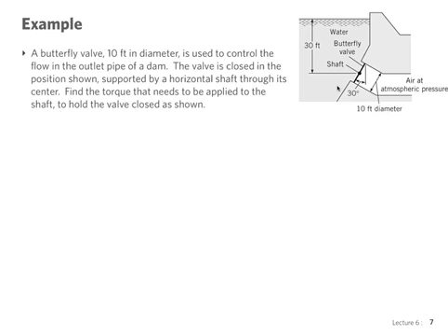So our solution is to use the hydrostatic force, and we can use shortcut number 1, which is to calculate the force by multiplying the pressure at the centroid times the area. The pressure at the centroid is gamma h at the centroid.